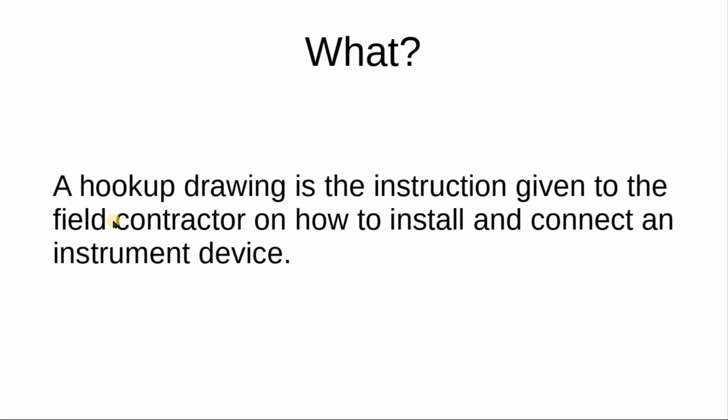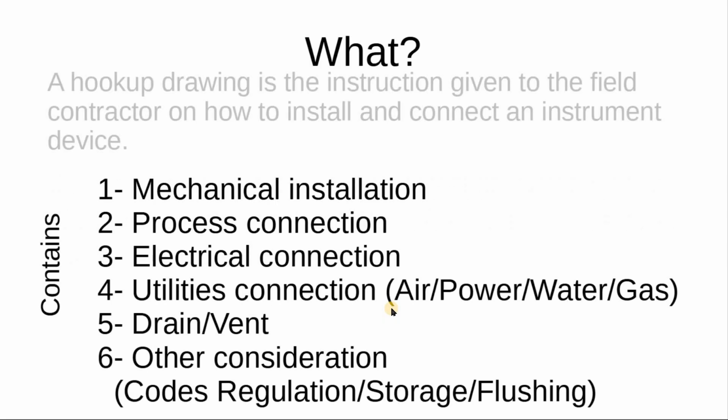So what is a hookup drawing? A hookup drawing is a drawing we give to the site contractor or the field contractor to address how he will install and connect a device, a pressure transmitter, a temperature transmitter, DP, whatever. So that is the main idea of this drawing.